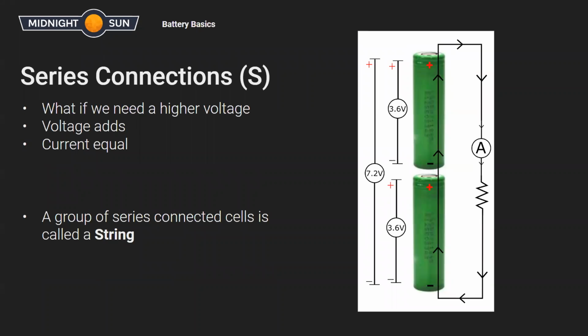So there's no single battery that we can just buy and put in the car to power it. So we actually have to connect the cells in different ways to get the proper power that we need. So you can either connect them in series, as shown in this diagram here, where the negative terminal goes to the positive terminal of another battery. And this will increase the voltage at the output.